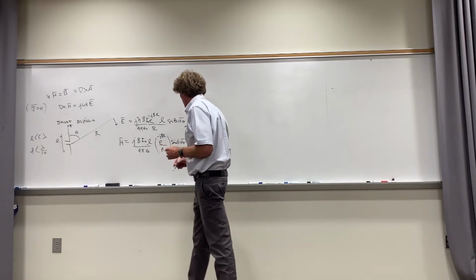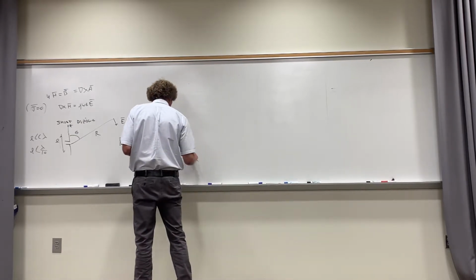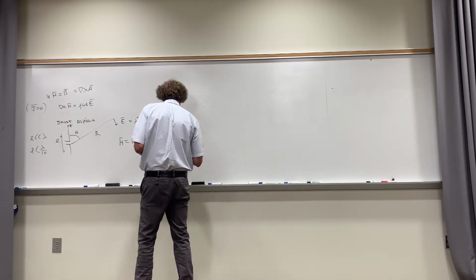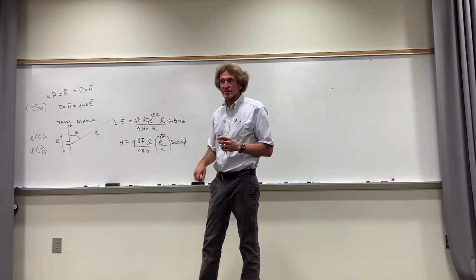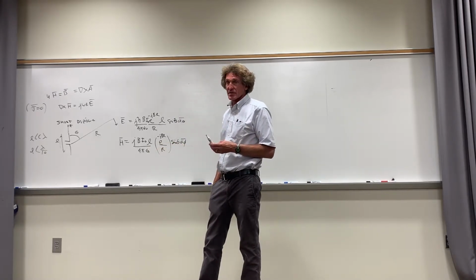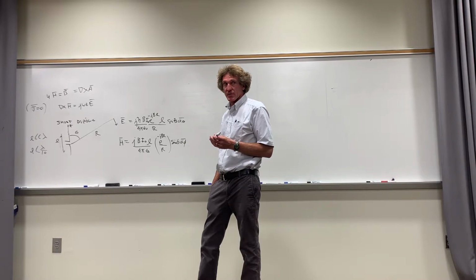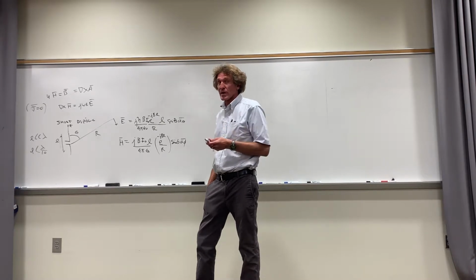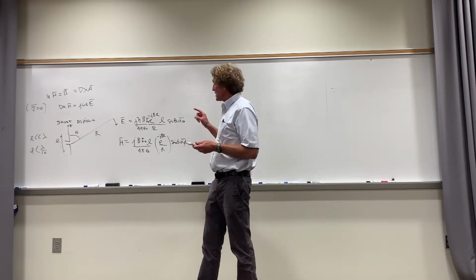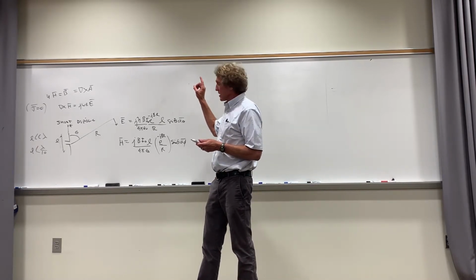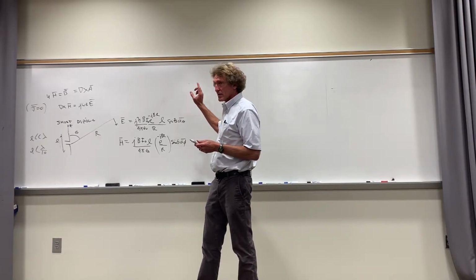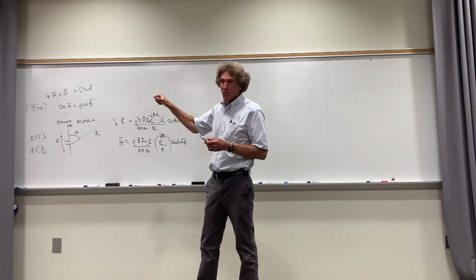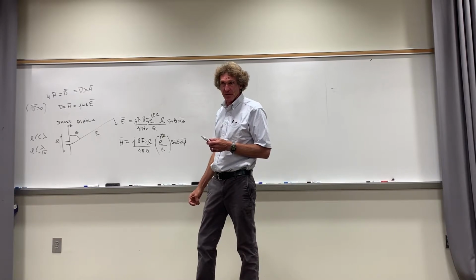So that's the H field, but it's not a theta, it's a what? Phi, right? Now it's not in the theta direction, it's in the phi direction. We're in spherical coordinates here. Do y'all agree with that? It's got to be perpendicular, and E cross H has got to be the direction of propagation. Well, E is theta, H is phi, and then we have theta, phi, rho. Are you with me? Okay.